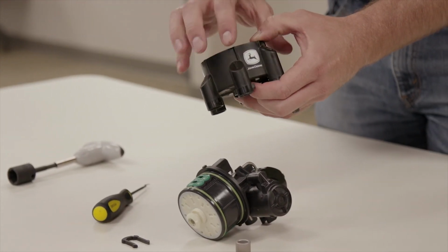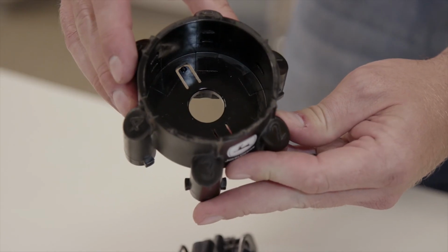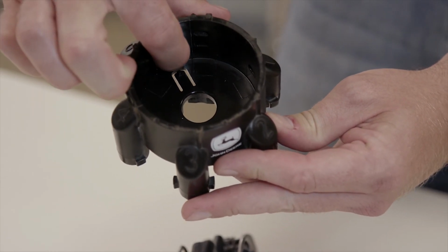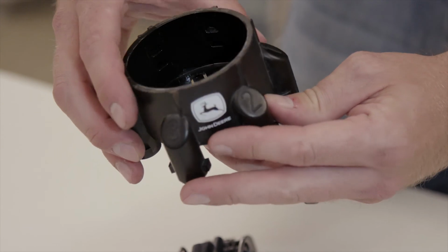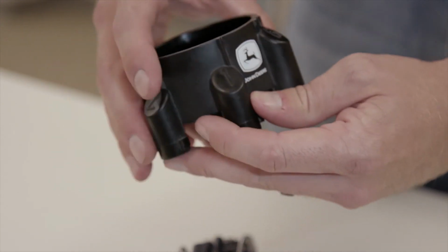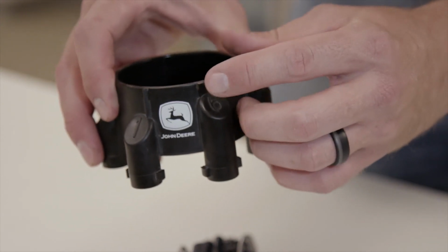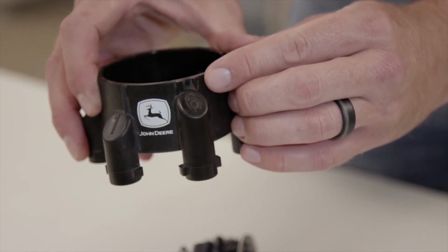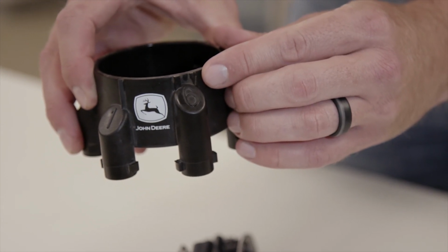Here as we look inside the turret, you'll notice the 1 position has 1 hole and the 6th position has 2 holes. That's going to correspond to the same features that are available inside the ExactApply nozzle body. 1 is going to be a short stem on the outside, 6 is a tall stem with 2 notches corresponding to the same features.